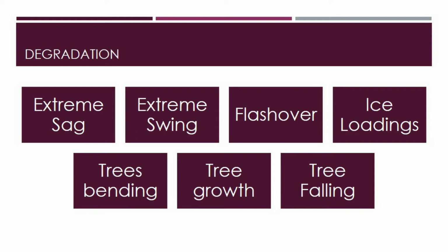When minimum clearances to the ground or grounded objects are violated, or when the structural integrity of the pole is endangered owing to soil erosion or ponding near the pole bases, bad or very poor circumstances might occur. And when a utility's access to the equipment for maintenance and operating activities is blocked, we will assign a condition of bad or very poor in the case of underground cable right-of-ways as well.